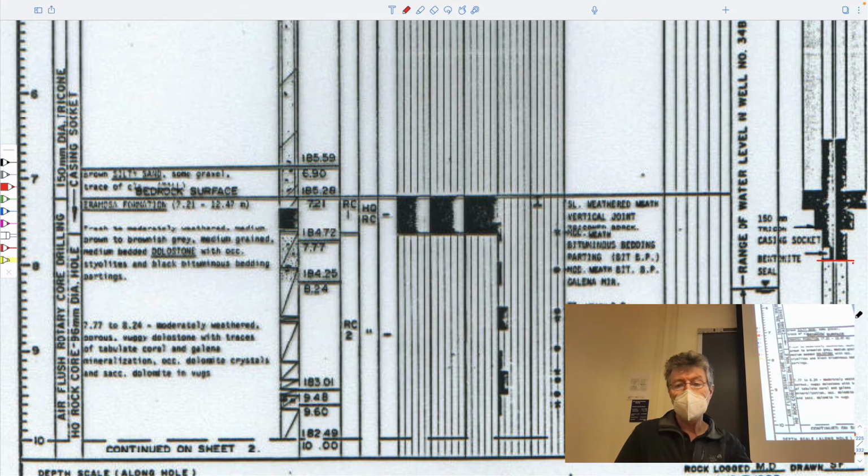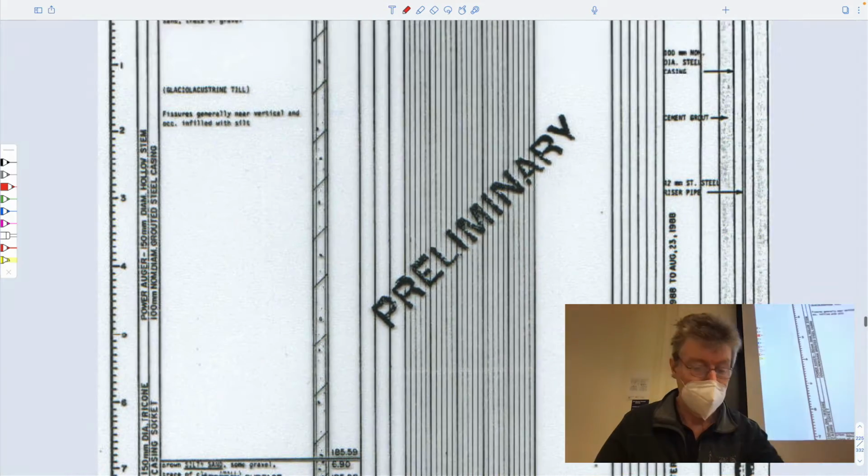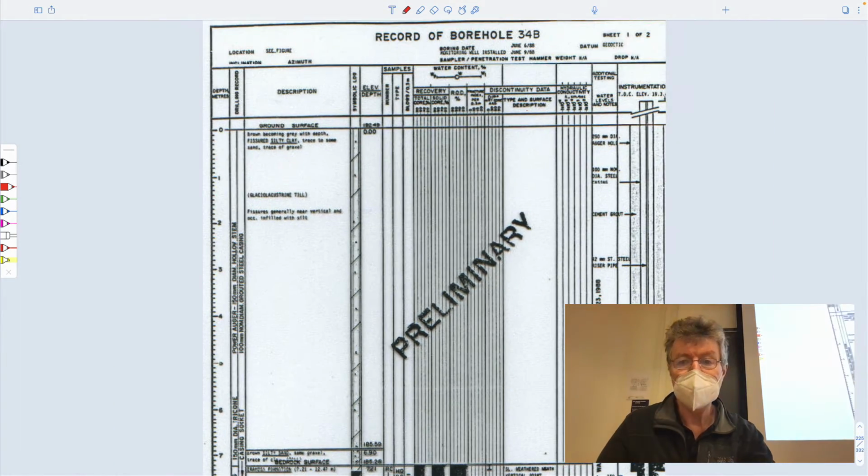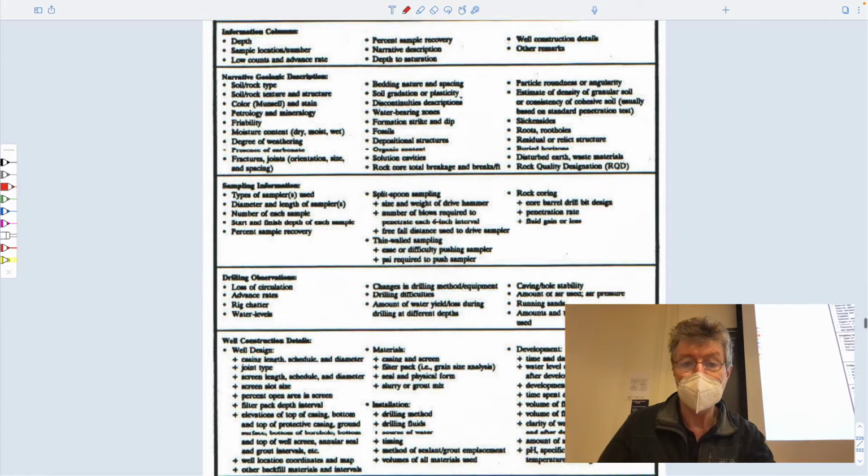So the flow regime that you're able to sample fluids from in this part, and to measure inflow or outflow from, to measure permeability, gives you permeability specifically for this portion of your well bore. It doesn't average it over the full length of the well, which might be many tens of feet, but allows you to get something like a 6-foot length, 2 meters in this particular case. And you'd want to record those data. So that's a typical borehole log that you'd have.